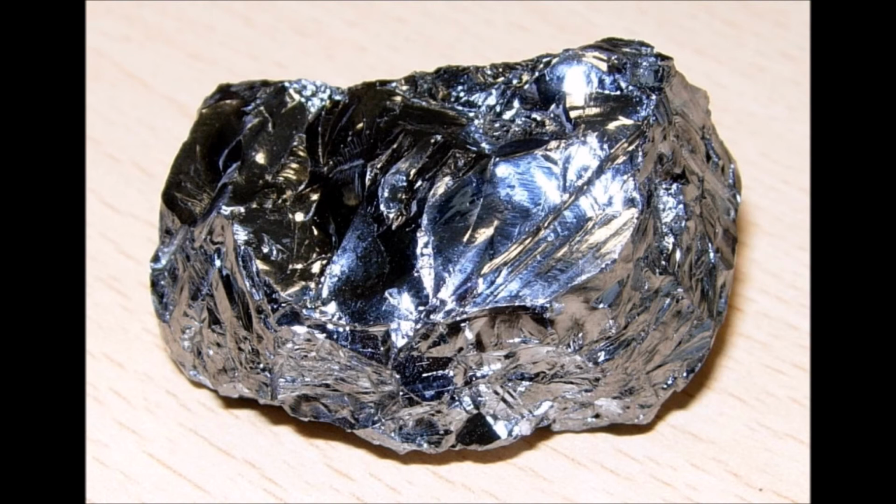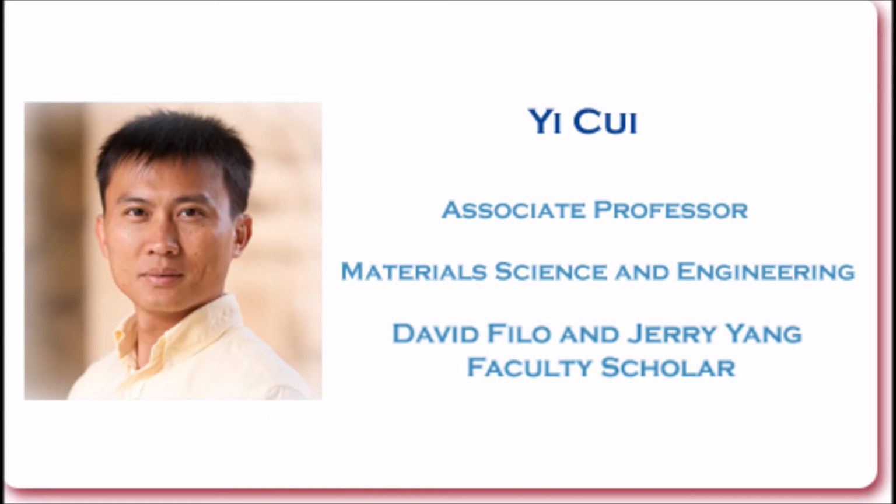The downside is that silicon films tend to expand when absorbing lithium ions during charging, and shrink again when releasing lithium ions during discharge, leading to pulverization and fracturing of the anode and a short life for the battery. But recently, a group led by this man at Stanford University has used silicon nanowires to create an anode that does not have this weakness.